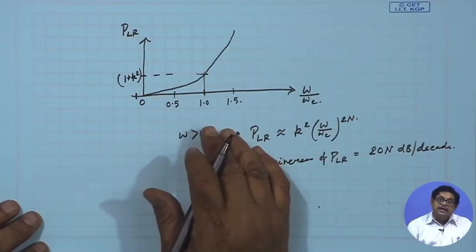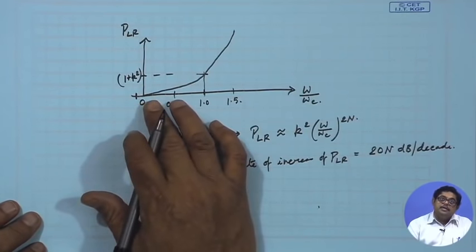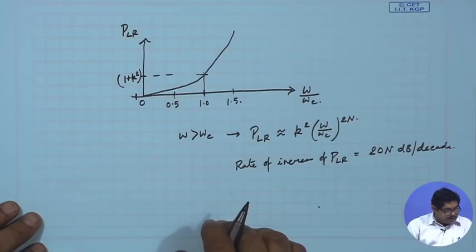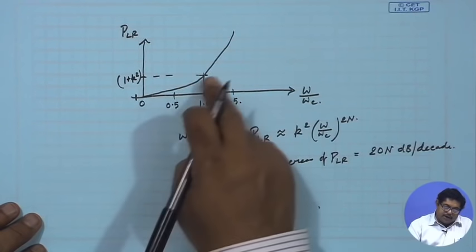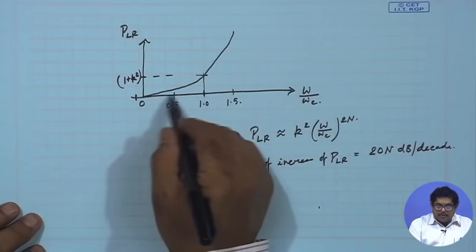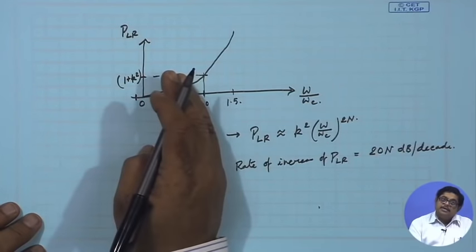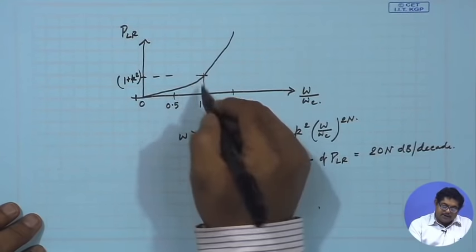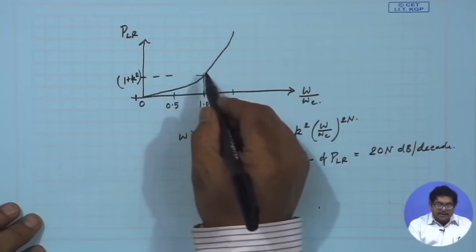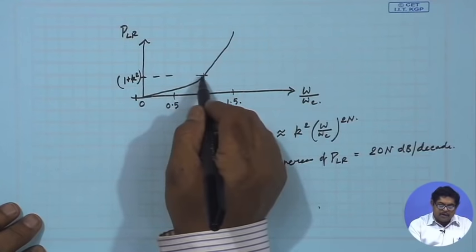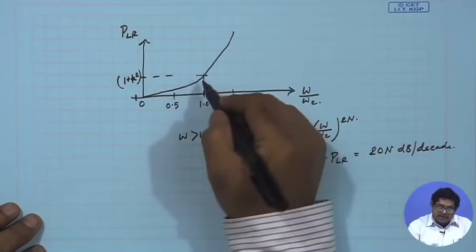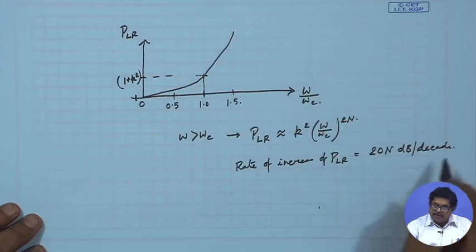So, we see that here attenuation, that means alpha, increases monotonically with frequency. But we know that at the lower side of the pass band it is not much, but at the band edge, that means near cutoff, it is increasing. I can always specify where the level will be fixed, clamped, and this rate of increase is 20 n dB per decade.